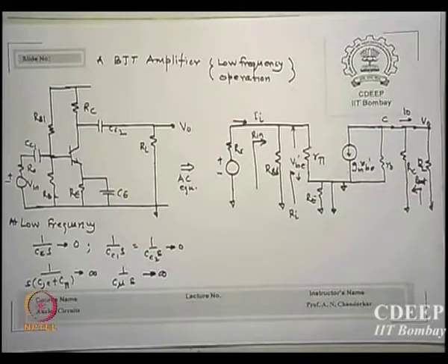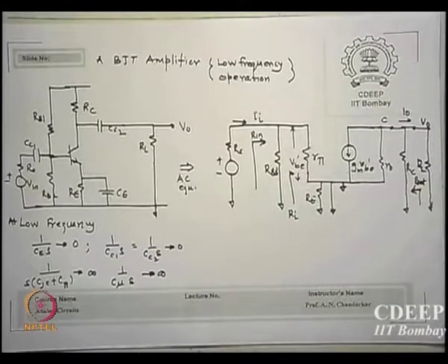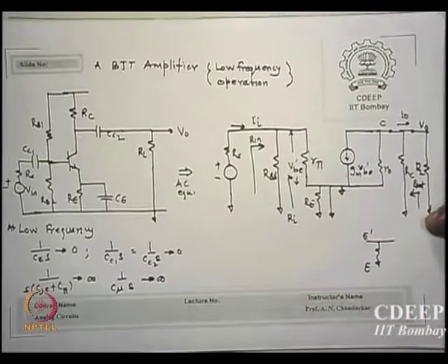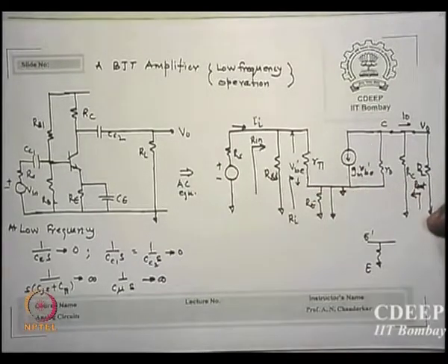Oh yeah, I told you, actually it is VB dash also. I told you that actually there is a small RE resistance, isn't it? Emitter resistance is obvious. So the emitter is not exactly the lead output. There is a small RE resistance there, parasitic. So we gave a name, emitter dash, inside to separate it from the actual emitter lead outside. I repeat what I said. This was emitter dash and this was actually the emitter lead outside. This terminal was given earlier in books by Shockley, the person who actually gave the equivalent circuit, he called it emitter dash. So base to emitter dash is VB dash.